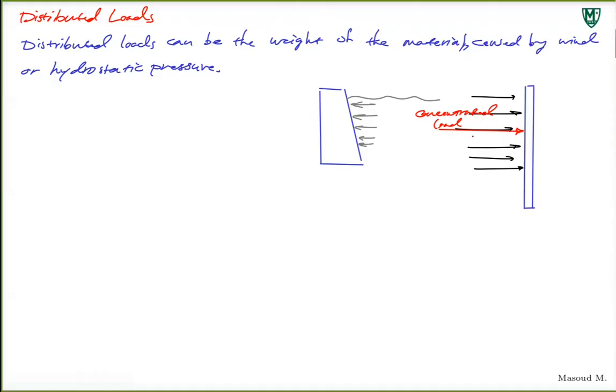But the question is where to put it. How far do you have to put it? So this is the distance. Where should I put it? And that would be the centroid of the area for the profile of the load. Explaining too much. Let's just put in four words and then we'll look at an example. We can replace distributed load.